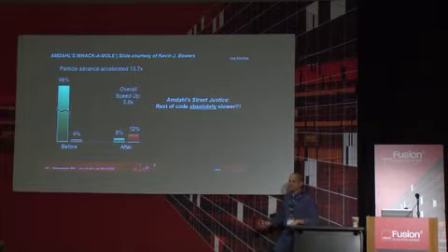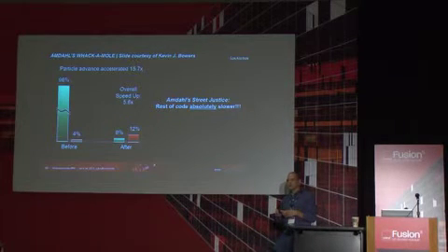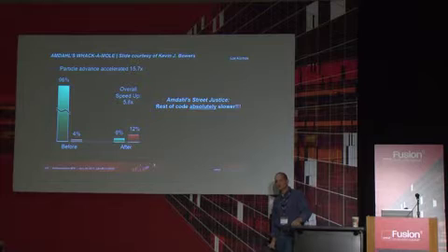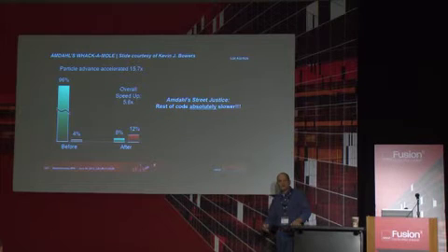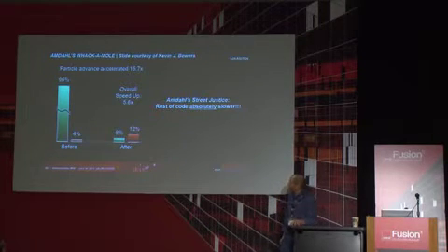The reason for this, as has been explained to me, is that in order to get everything to fit onto the Cell processor that they wanted, they stripped out a lot of the out-of-order logic and instruction windows for the Power Processing Element. But we were using a compiler that wasn't able to optimize for this now essentially statically scheduled core. And so it got pretty bad performance.